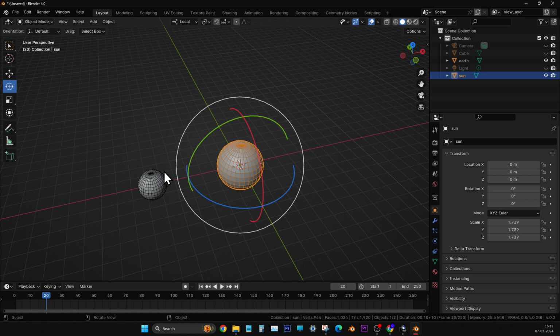Only once we give that and you press the play button in the timeline, it will play. Blender is saying that at the first frame you gave rotation 0, and in the 100th frame you gave rotation 360. Now you have pressed the play button, so it will play from 0 to 360, 1 2 3 4 5 6, like that till 360. Yes, it is possible.